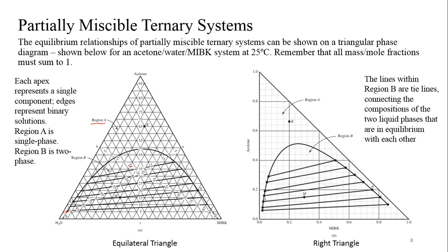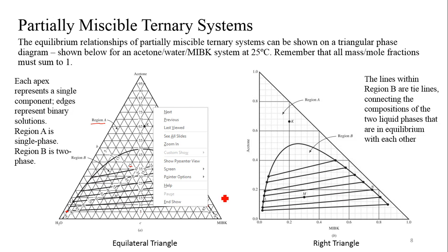Since that's the case, we can use a tie line. We're very close to the tie line shown here, so we should be able to come up to the other side and read off the composition of the extract. Looking carefully, we're beyond 85. I'd probably be a little less than where I drew that dot if I was careful.